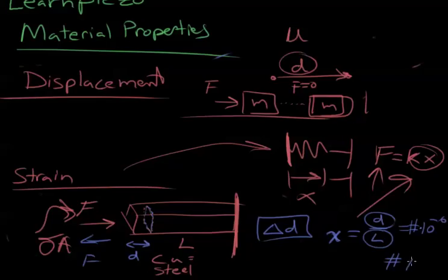We often denote it as micro. But again, you don't say like 20 micro. You say 20 micrometer over a meter. So these cancel out. This is just a traditional way of writing strain. You write micrometers over meters. The meters cancel out, and you're just left with micros. And you realize that this stands for 10 to the minus 6. So that was strain.